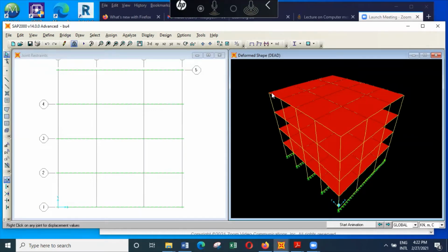And you can see it shows a big deformation vertically, and it has deformed 5.5 millimeters vertically. Whereas here it has moved by 5 millimeters vertically. So when you look at the graphics, you see a big deformation, but it can be only a very small one because it's a relative deformation. And here you can see the structure has moved downwards vertically by 5.3 millimeters.